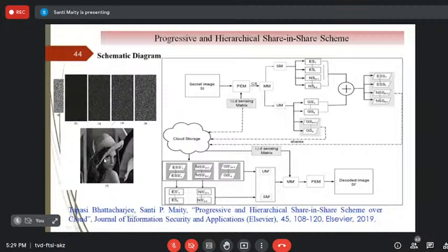So what is done, instead of doing compressive sensing in your sparse representation space, looking for DCT, DWT and all this, we think of a sparse representation in the original domain. You have an image, and you represent a prediction based image. If your prediction is good, the difference between the original image and the predicted image is very small, and that gives you the sparse representation. So if you would like to share this image as a secret, instead of sharing it in this form, you just calculate a predicted image, take the difference, and if your prediction is good, it would be worthy, and you can go for this.